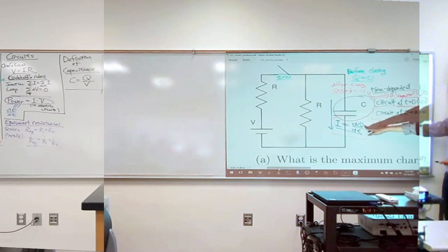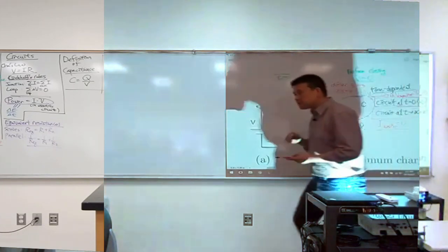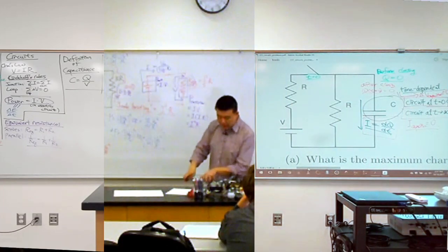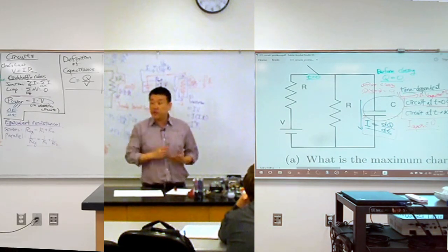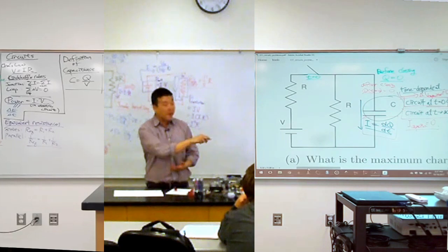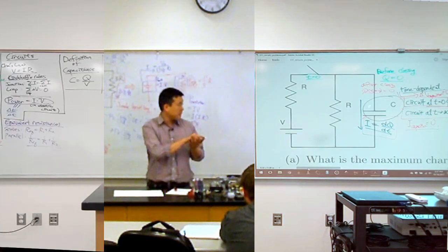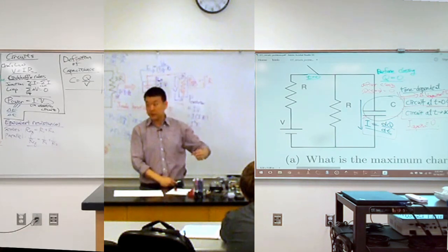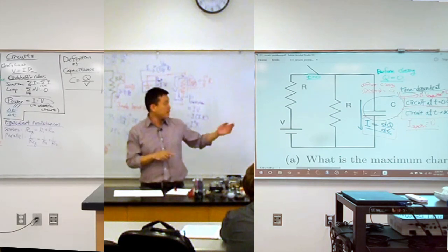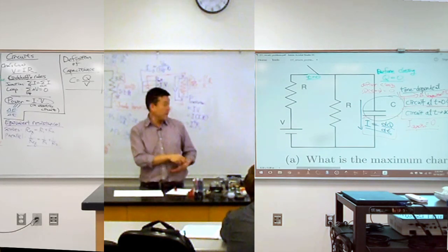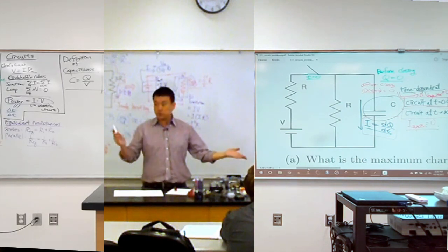You can simplify the circuit with the help of these two rules, either by replacing the capacitor with a piece of wire, meaning 0 voltage change, or by replacing the capacitor with an open circuit, meaning 0 current flowing. Which one you use depends on the circumstance.